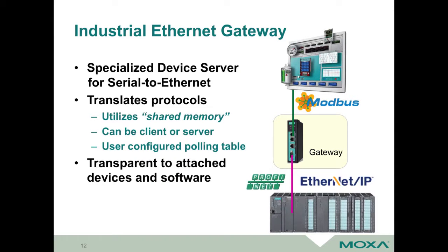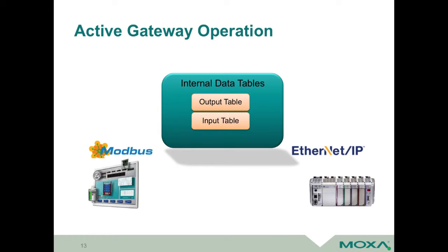You can go out to a third party and buy a plug-in third-party module to drop in that PLC rack to give you that other communications protocol that's maybe not native for your specific PLC vendor. I've seen some folks in past years put an embedded computer in the panel and use that computer as a means to do protocol conversion. Of all those options, I think this is a great one to think about: having a gateway that fits in there, and this uses a shared memory concept to make both devices talk so that you don't have to make changes on either side other than the memory addressing. To give you a better idea, let me go to the next slide and show a little bit about how that might work.